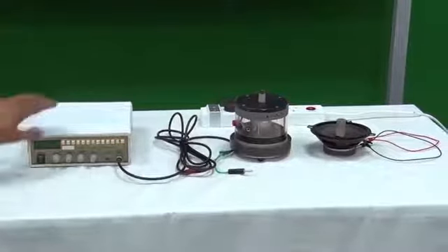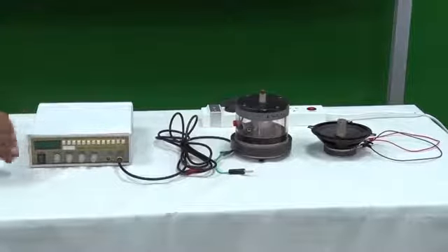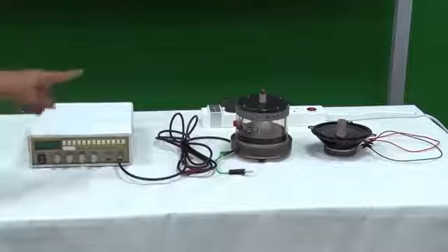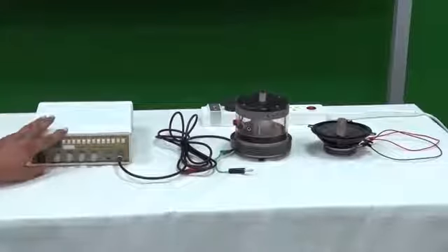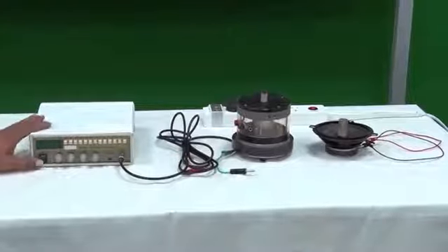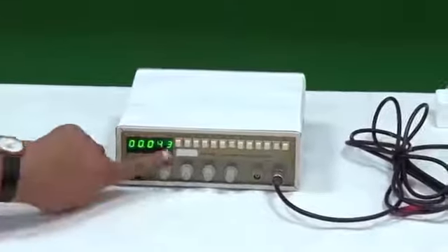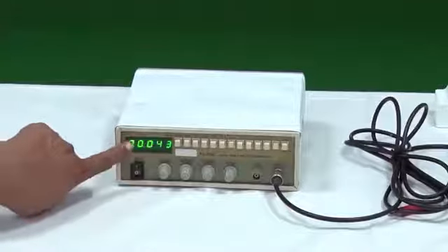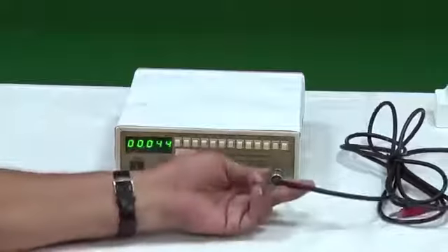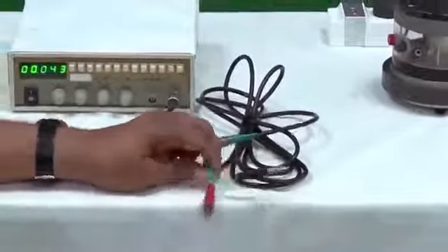So, it operates on AC, but it is not using that AC, because that AC is 50 hertz only, and it is producing its own AC at a very different frequency, derived from the DC voltages which are converted from the AC of the power supply, and then that DC is used for this oscillator circuit. So, if I put it on, you have this display which tells how much frequency it is generating. It is generating AC voltages, and that AC voltage is coming here. This is the output point, and finally these are the 2 points. So, here that AC voltage is coming at the frequency which is desired.